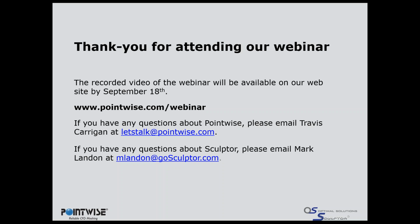Okay, so one question is, how did you refine the mesh on the bottom wall and all the way behind the car? Is it a separate domain face? Underneath the car, on the bottom wall, basically what I did is I created a separate domain that's just right underneath the car that is refined. I basically used the cell size that I had used on the lower surface of the vehicle, on the underbody, and that's the same cell size that I used for that domain right underneath the car in its immediate vicinity. And then elsewhere, it propagated out and increased in cell size.